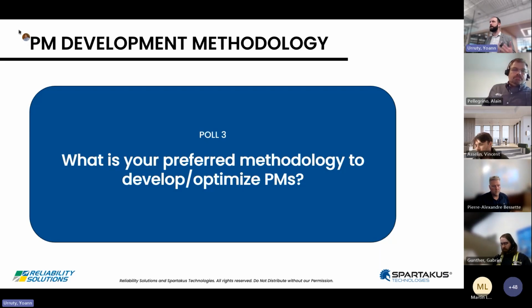So of course, multiple recipes, different results, right? Typically, what we would say is that if you have highly critical, mission critical pieces of equipment with a high lead time when it comes to getting the parts in stock, or highly expensive parts to replace, of course, you'll choose RCM or FMEA.